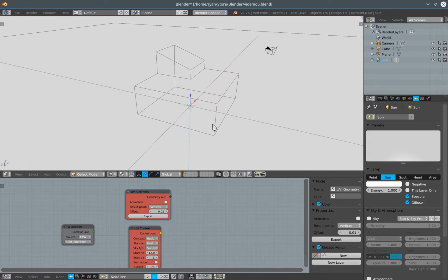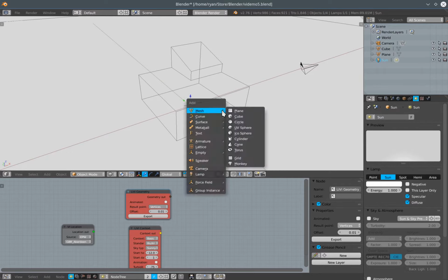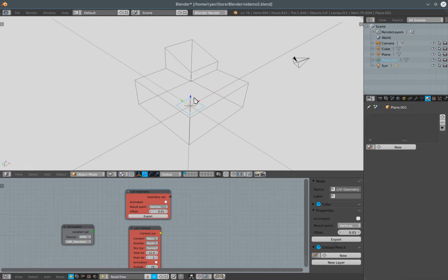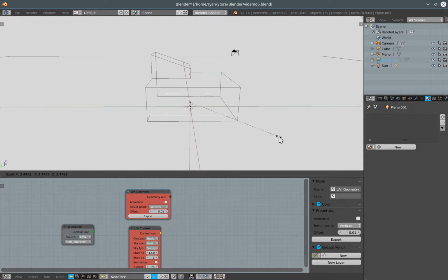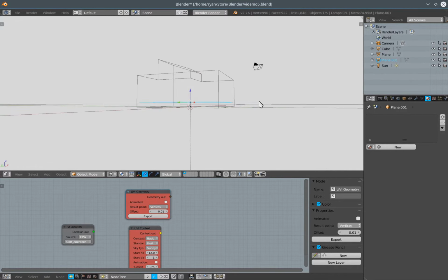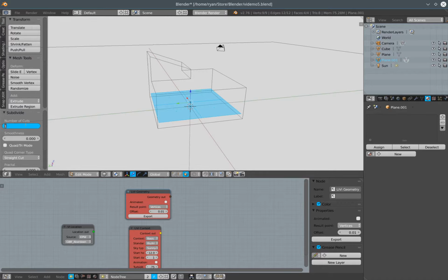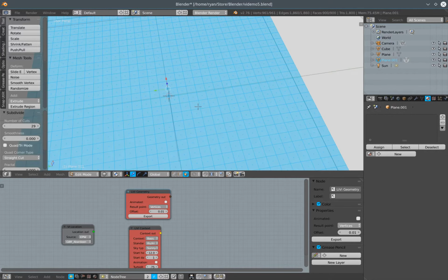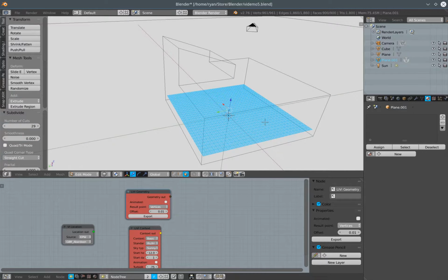need to create a sensing plane upon which our lighting metrics are going to be projected. So I'm going to create a new plane, put that slightly off the floor, scale it up to almost the floor size, and as we did for the shadow study analysis, I'm going to subdivide that plane so that we get lighting metric results at each point within the sensing plane.